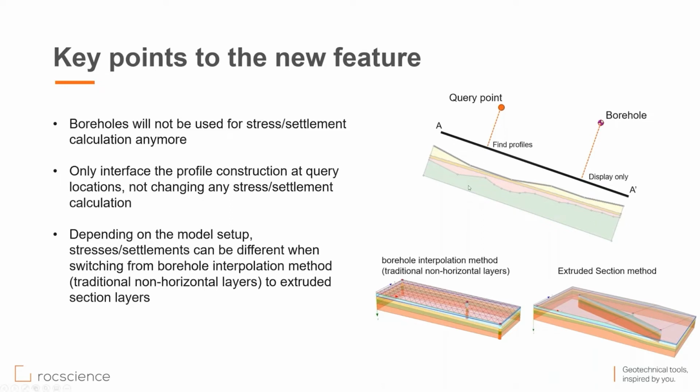This profile is then passed into the stress and settlement calculation. Existing borehole entities also make projections to the section line and display the borehole layerings in the section creator, but like I said previously, they will not be involved in any calculation. So after all, the stress and settlement calculation method remains unchanged, and only the way the query profile is constructed has changed.